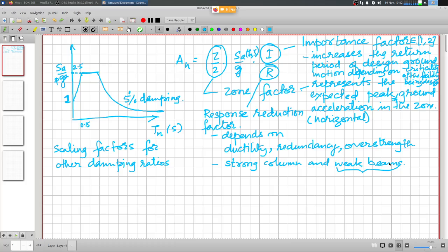And that is the problem. I may design the complete frame using strong column and weak beam assumption, but if the actual reinforcing steel turns out to be much stronger, it is quite possible that reinforcements in the column might come from a different batch, and reinforcements to be used in the beams might come from a different batch, right?